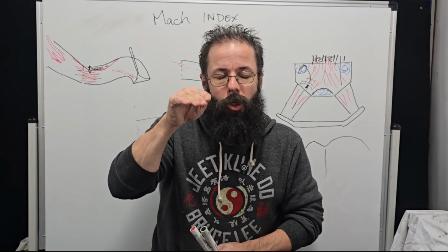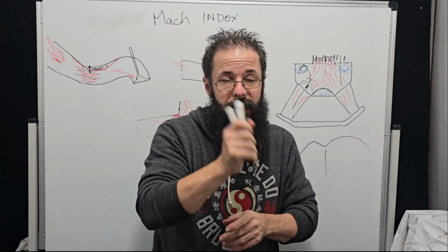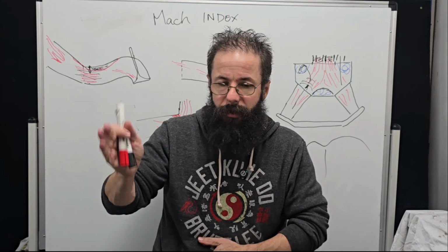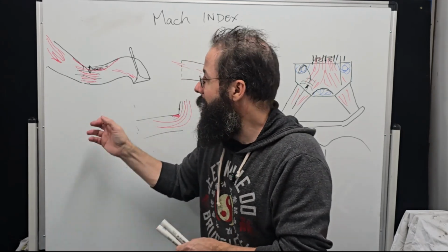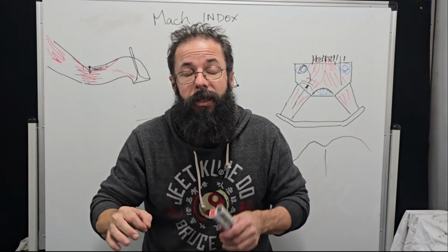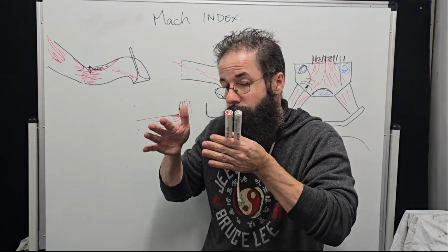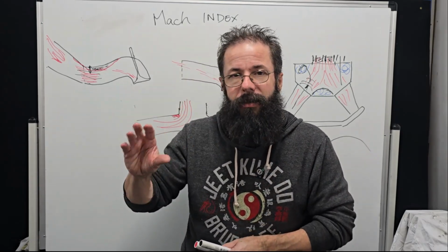And they were showing how different angles, straight versus curved, affect individual volumetric efficiencies on each cylinder. And it comes down to this, that we're going to get density variations in roughly the same speeds, and due to that inertia, we're going to get different density variations.